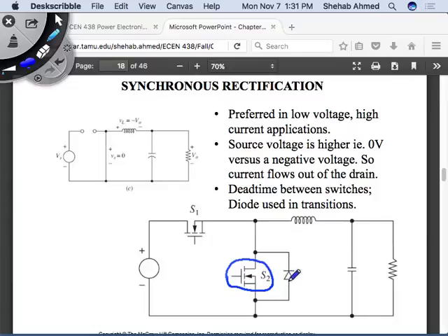So this is typically used in applications where we are trying to improve efficiency. Why is that the case? So these diodes have a forward voltage, right? V forward of the diode is a certain number, 1 volt, for example, for power devices. The 0.7 you were studying before in 325? For power diodes, it's a little bit more than 0.7, typically 1.2, 1.3 volts is the V forward of the diode, right? So if you have any current flowing through the device, you'll multiply the average current multiplied by the forward voltage, and that will give you the average power loss through that diode, correct?